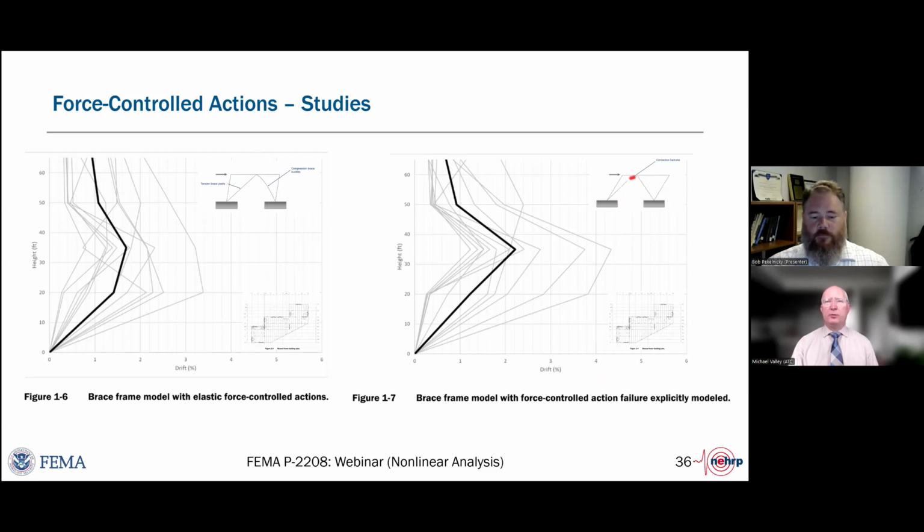Onto the unacceptable response drift limit. Is the 6% drift ratio limit based on MCE ground motion scaled to the ASCE spectrum? It is based on whatever seismic hazard parameter you are looking to use for your evaluation. It is an unacceptable response specific to the seismic hazard intensity that you're inputting into your model.